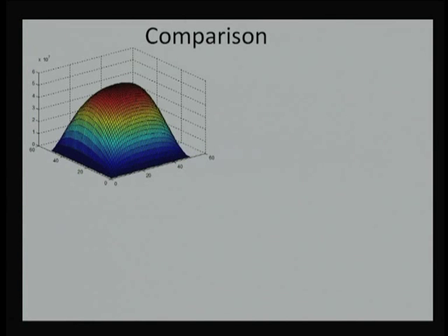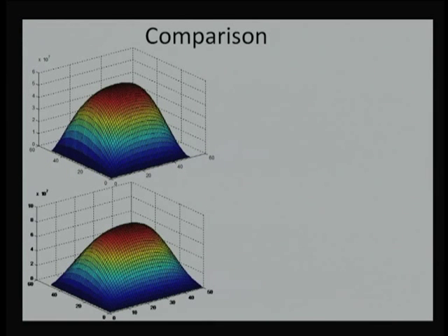Now, this slide is going to show the comparison: is there any change? This is done with the half node calculation, where we are computing the pressure distribution and the effect of viscosity on the pressure, that is, with viscosity thickening. In the first figure viscosity thickening is not accounted for, while in the second figure viscosity thickening is counted.